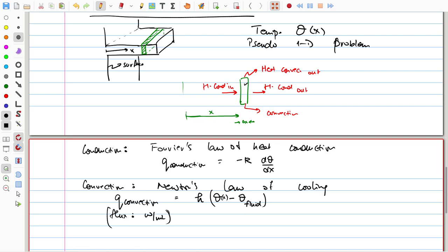So k being higher means that for the same temperature difference, you will see a higher heat getting conducted in or out. This was given by Fourier, and remember that this is actually not a law of nature. It was given because it works well, so it's called the gradient diffusion law. Typically, it's the first derivative that is responsible for conducting heat in a diffusion process. Heat conduction is also a diffusion process, but this is not a law of nature. We have not been able to show this using some other physical law. It was just a mathematical hypothesis, which works, and is still working today.